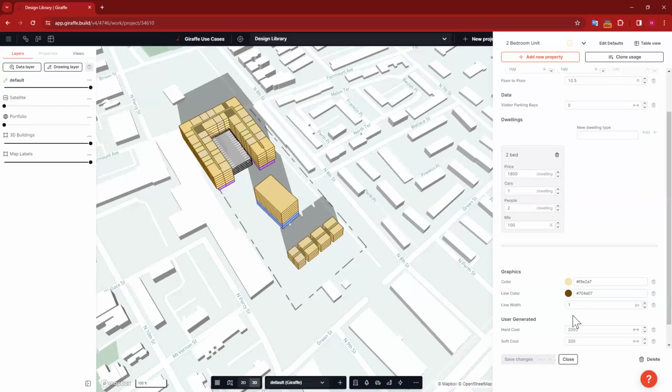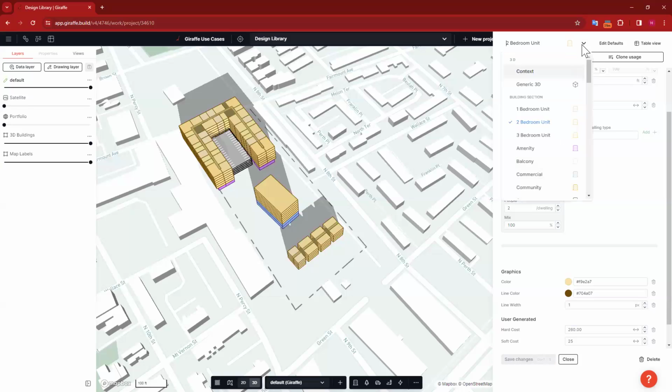And what's great about this is, right now, this is going to take me a little over an hour, probably. That is what we have scheduled for this webinar, to go through and edit all of these usages. But once you do it once, it's saved into your template, and then you use it over and over again. So you really should go through your main template that you're planning on using in Giraffe and fix all of your usages to match your company's assumptions, but you only have to do it once and then update as those assumptions change. This is not something that you have to do manually on every single project. It's something that you're doing once here as you go.